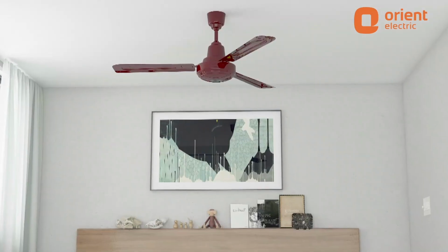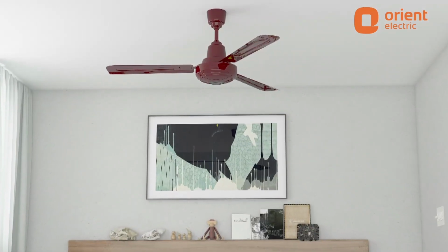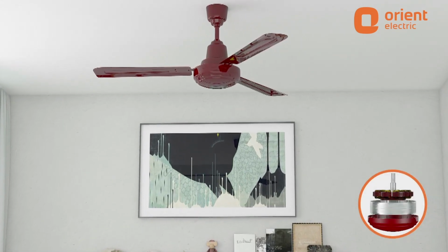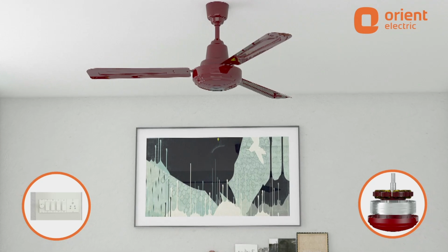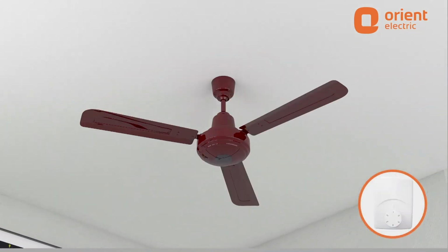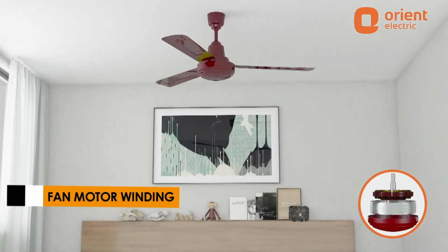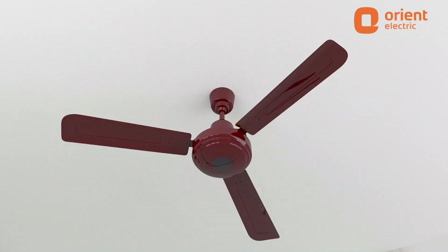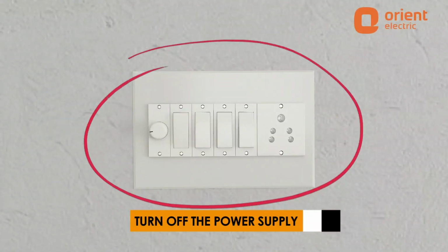The failure of a ceiling fan to start can be attributed to many reasons, which may include jamming of motor, no power supply, or low voltage, wrong or loose connections, defective capacitor, open circuit in regulator, and issues with fan motor winding. Before you start the inspection, you must first turn off the power supply to your ceiling fan.